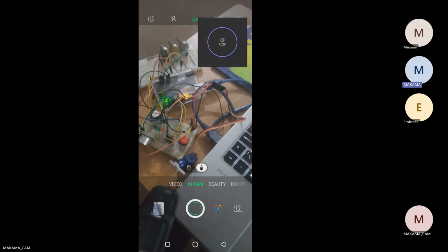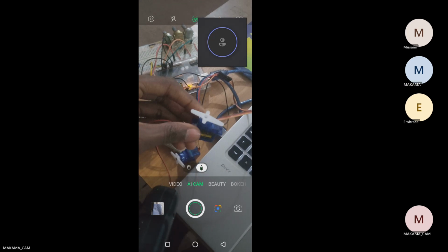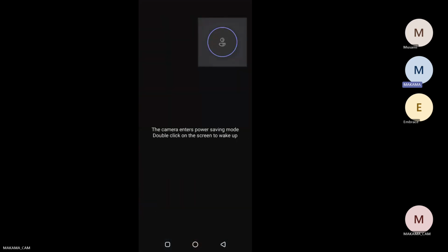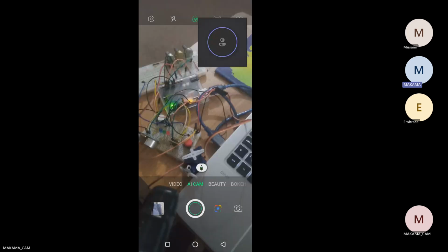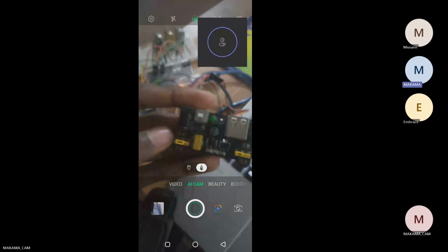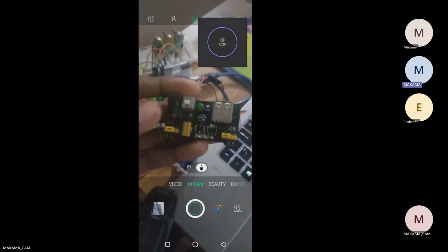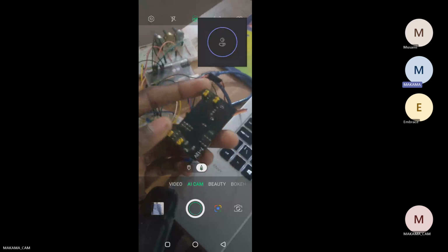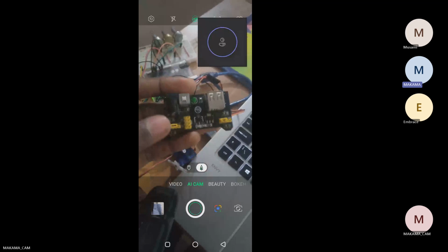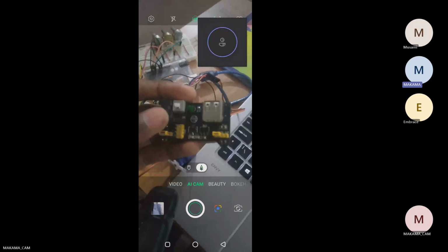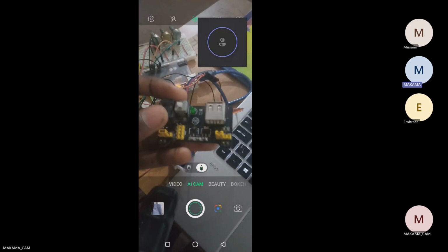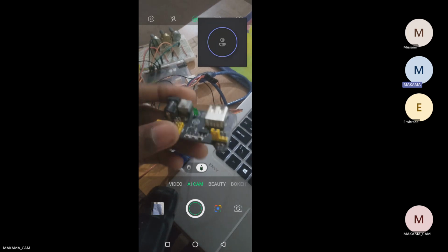So what should you do to avoid that? You can use external power supplies. When I say external power supplies, I don't mean going to buy a transformer or something. What I mean is this external power supply. This one is also an external power supply. We call it the breadboard power supply. I know it will be difficult for you to get here. Maybe you have to search online, because I also got mine online, though this one has spoiled. I'm having so much difficulty using some of my power-consuming devices like the servo motor, because I burned this device.